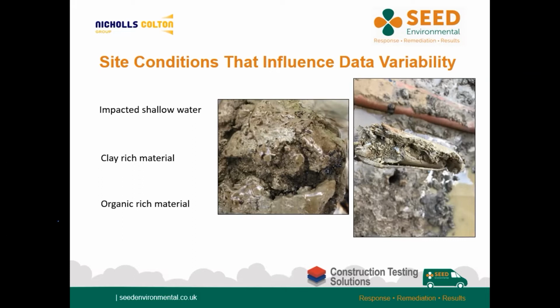Further to this, if the groundwater is heavily impacted and has a layer of free-phase product present, this product can be smeared across your sample as it is retrieved from below the resting water table. When this has happened, it is easier to see with clay-rich soils, which will have an oily sheen on the outside of the core, but when broken up, the core is visibly clear of contamination or even dry.